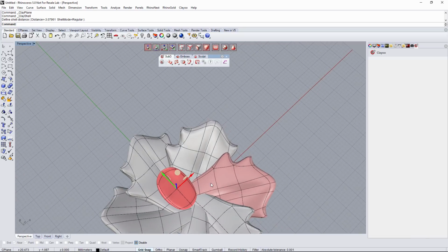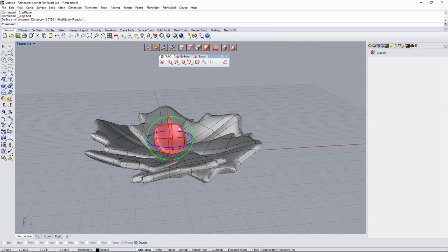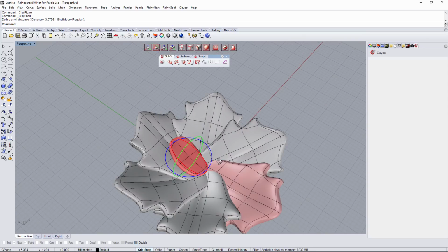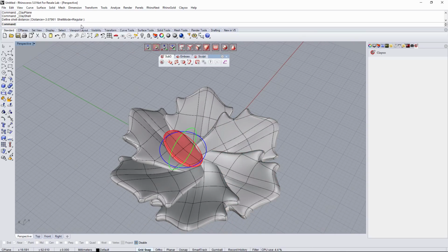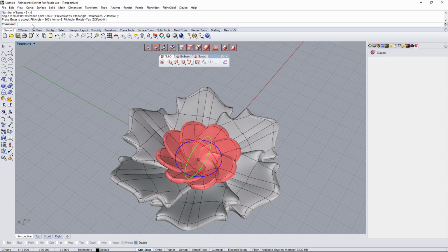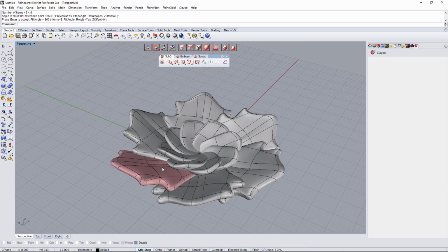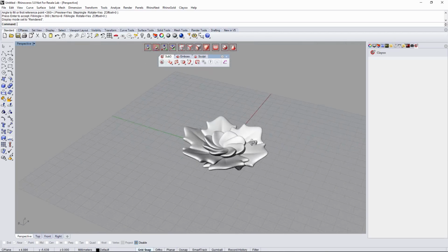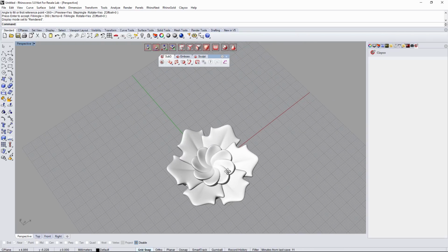So just place it where I want it to be, and I recommend you rotate the geometry a little bit in here. Okay, and from here again, just going for the array polar, center of polar 0,0 again, 6 copies, it's fine. In this case I can put, for instance, 8 copies if I want to. Enter and enter. Again, I can get this inner geometry quite good, that's gonna have a nice effect on my model.